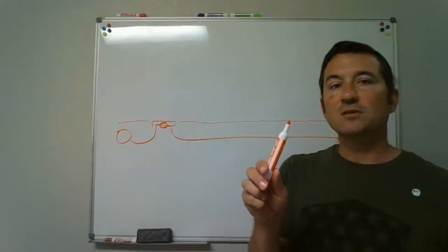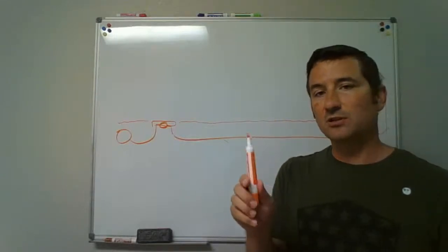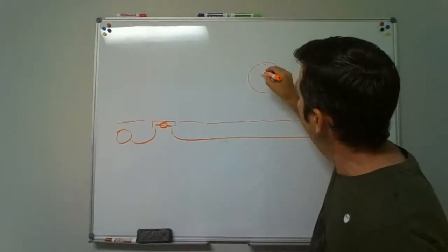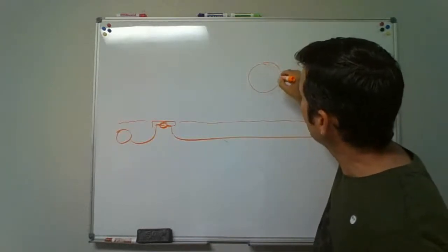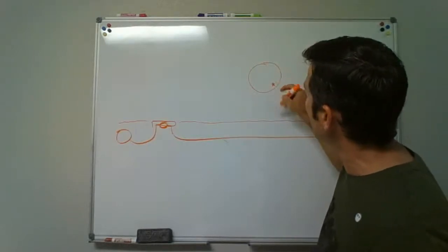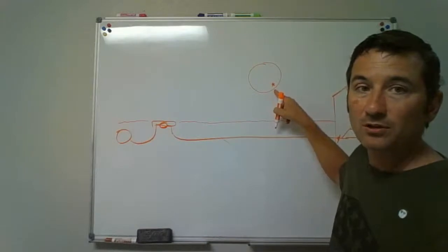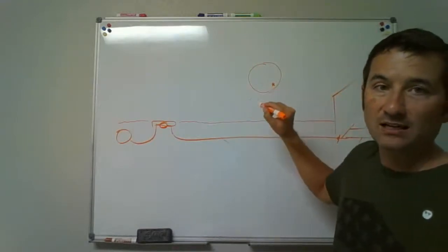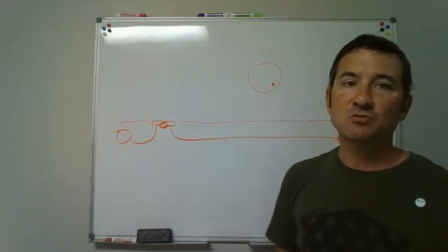And if you see the meter moving at all, there's also a little indicator. If you look straight down on it, there is a big dial that goes around. But then there's also probably like a little star or a little something over on the one corner. That's the leak indicator. If you see that thing rotating at all, that shows you indication of a small leak.